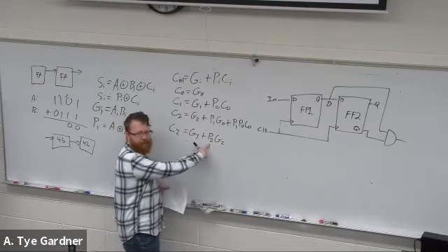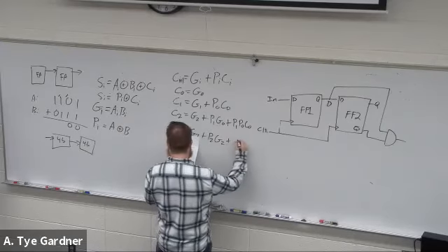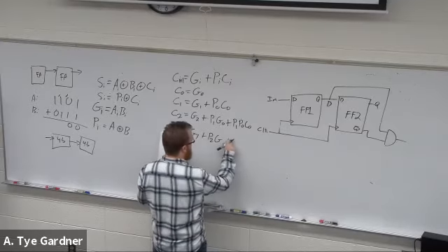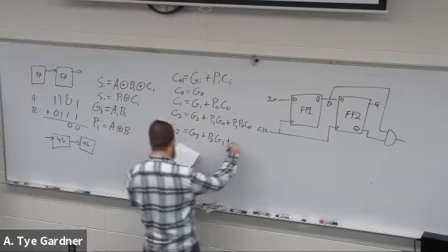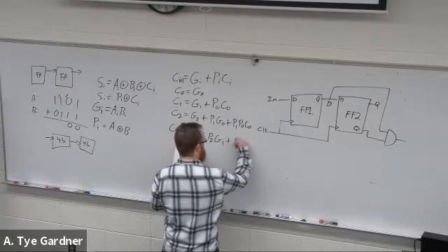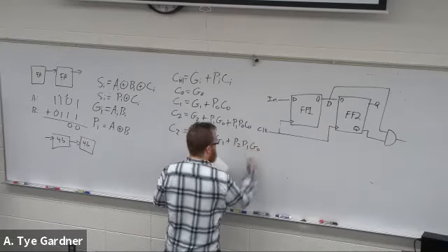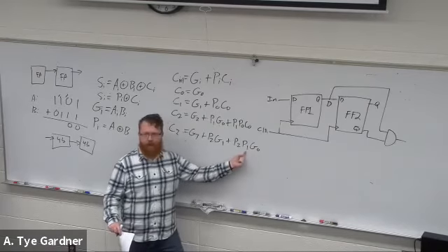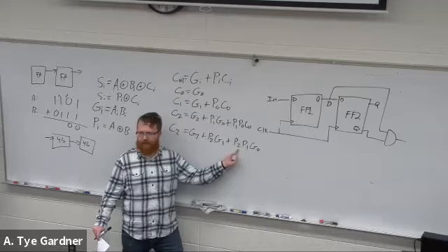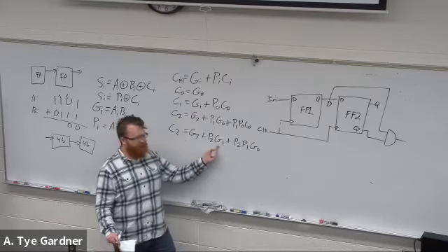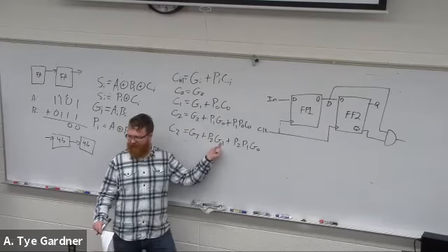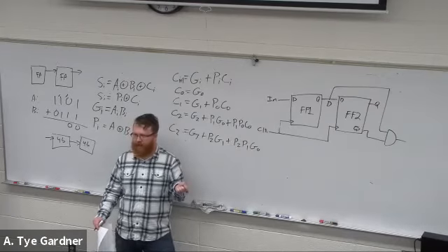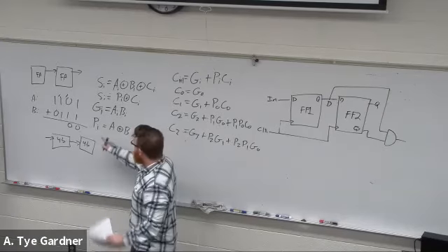G2 propagated with P2. Or, sorry, I got lost. All right, P2 G1. Did 1 generate and P2 passed it along? That's that question. Now this one is, did the 0th bit generate 1 and pass it to P1 and pass it to P2? Okay, so we're looking at all the possible places we might make its carry, and did we pass it along? That's why we're calling it these propagate functions.